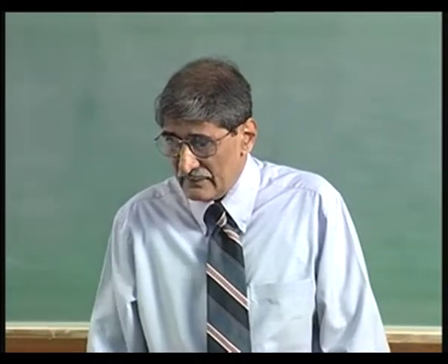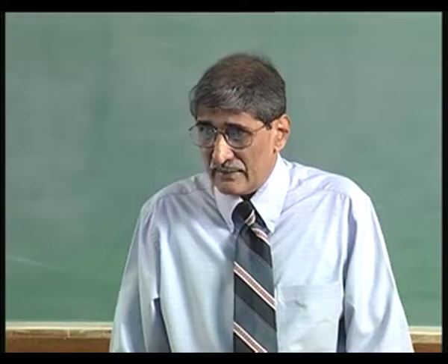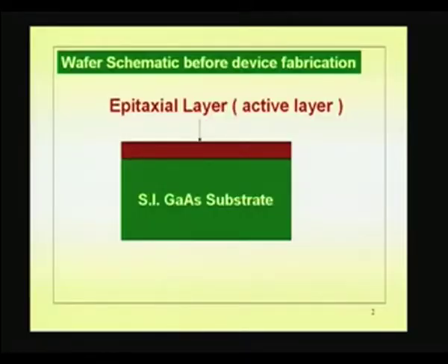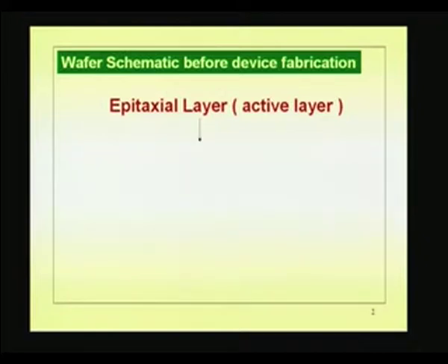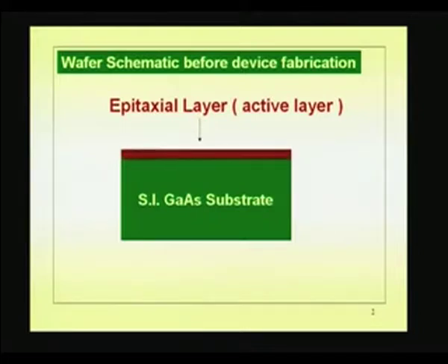now you see the growth, that is the substrate, and that red color or brown color is slowly growing here. Let me put it back once again, so that you can see it: gallium arsenide substrate, then on the top of that you have that layer slowly growing. That is the layer which is the active layer. In fact, I mentioned yesterday, if this is semi-insulating gallium arsenide that is chromium doped, before you put this active layer, you introduce a buffer layer, so that the abuse is taken by the buffer layer. In the sense, when you do high temperature processing, all the chromium that is present may go into the buffer layer, and the actual layer on the top does not get affected.